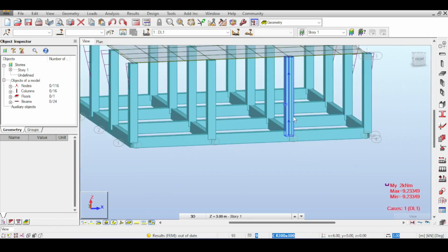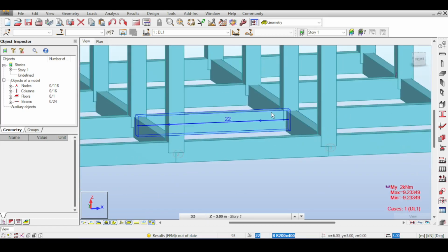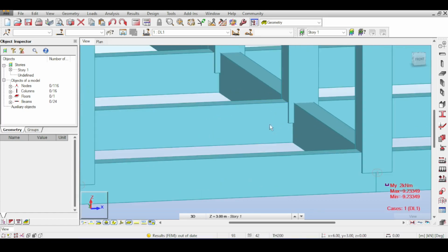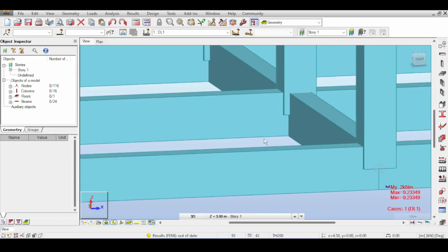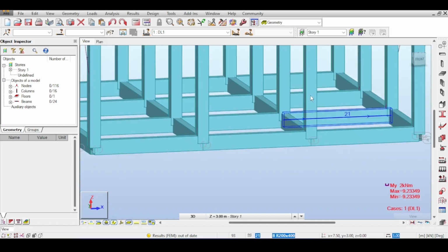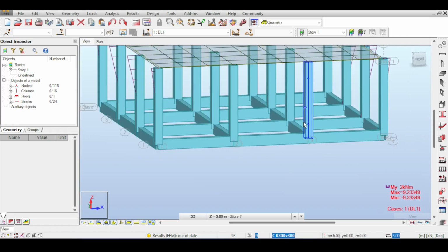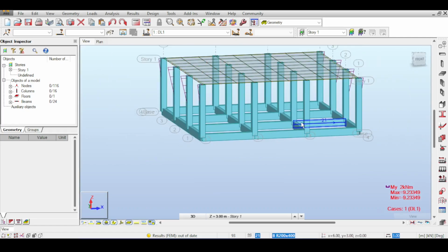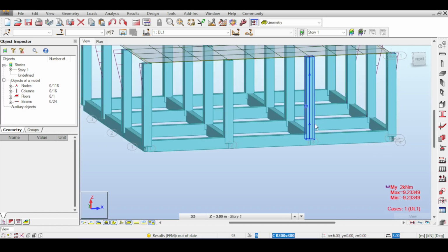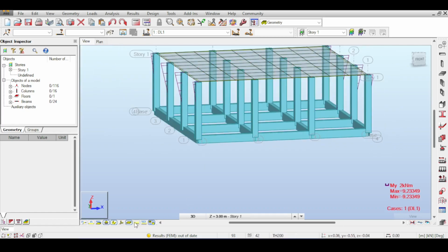But of course, Robot doesn't see this. Robot doesn't understand those practical ideas. Let me repeat that. When you implement this, you would dig your trenches and basically cast your concrete and fill the soil until 20 centimeters below the surface, because you want to cast the rest of the concrete with your raft. So this will never move, never say never, you have seen Turkey, but this should not move in the X and Y.